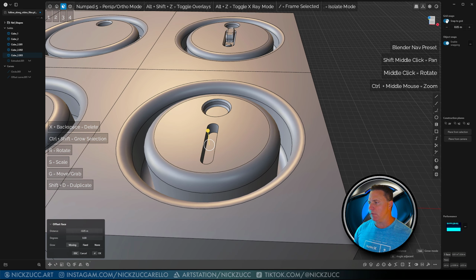So now I'm going to tap 2, hold down Alt and click on this, and hold down Shift to get the rest of it. And then now I should be able to either fillet or chamfer, either one, depending on what you want look-wise for this. I was going to do that there. I'll go ahead and tap 3, and I'll tap O to do an offset of this right here, like that. Go ahead and right click. So I'm going to select this part, and I could just push this in. That's fine, but I want to do a little bit of a taper there.